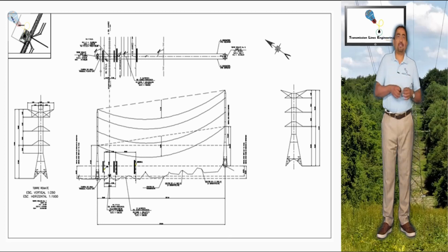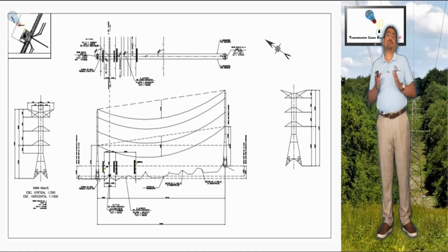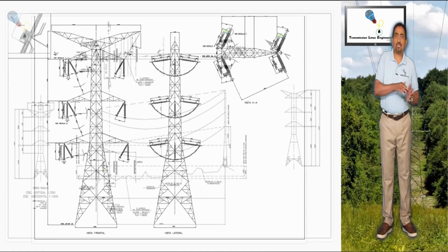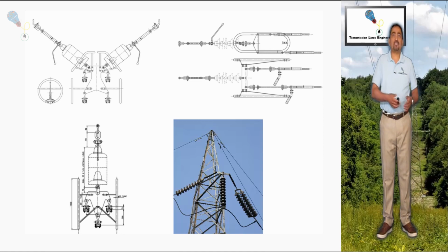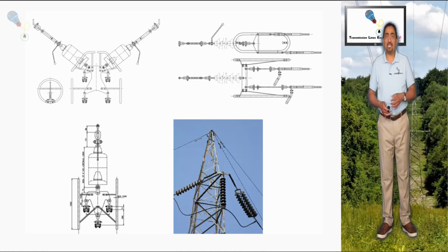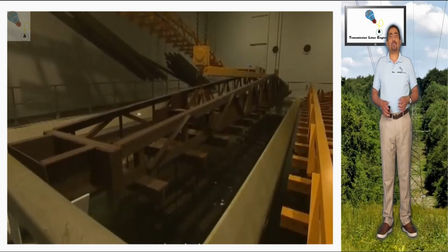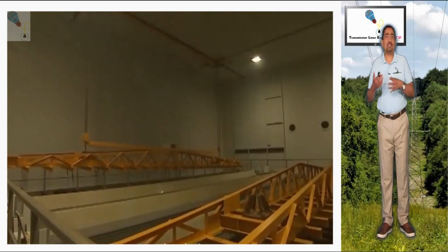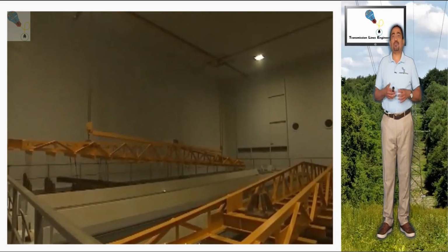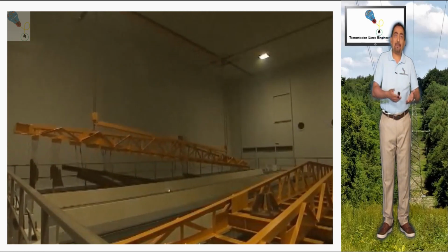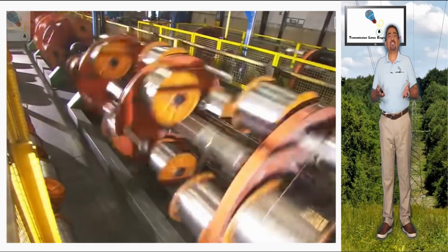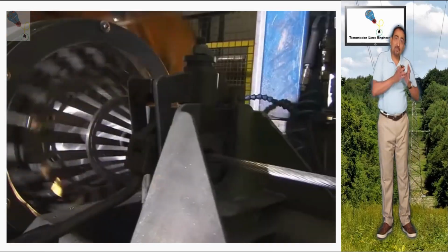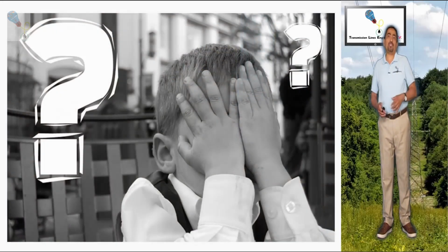As a step number 8, at the same time, the contractor develops the documentation related to the details of the structures to be used, hardware assemblies, grounding systems, and generates the first material list to start the purchase process. There are many materials with quite long lead times such as structures, cables, hardware and fiber optic. So therefore, it is a good practice to start this process as early as possible to avoid last-minute rush.